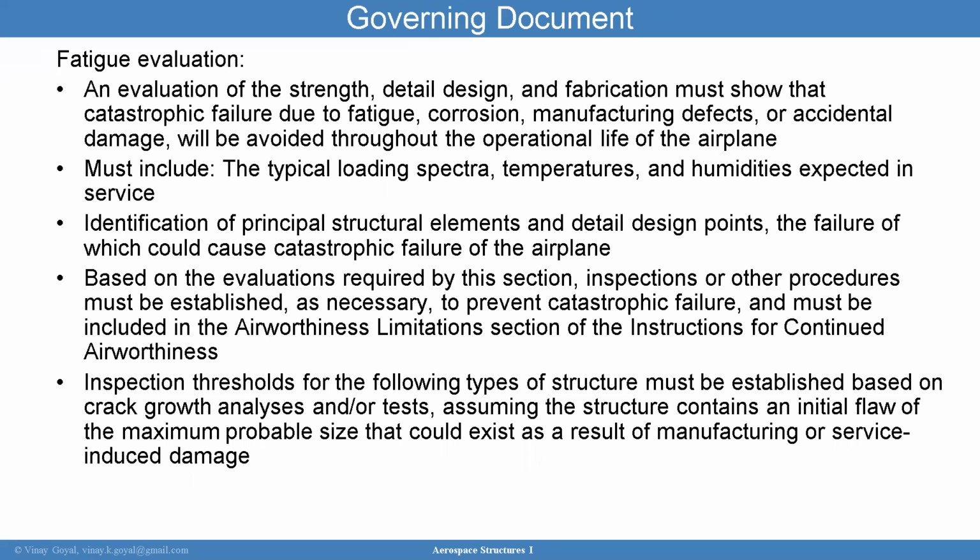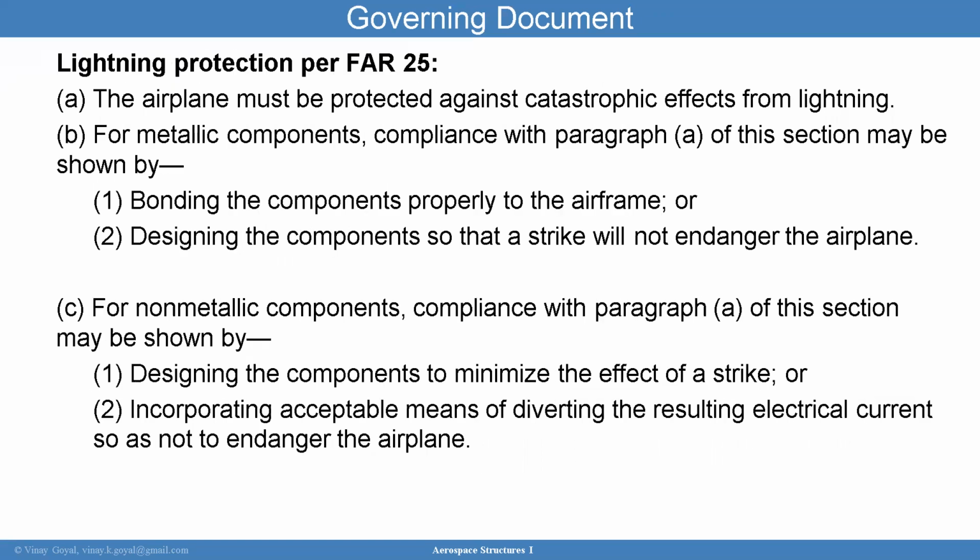So again, you need to make sure that you have identified every single point of failure that could cause catastrophic failure. You also need to define the load spectra, the temperatures, and humidities expected in the service life, because that can play a role in that test program. And so again, you want to make sure you're designing against catastrophic failure due to corrosion, manufacturing defects, accidental damage like impact damage, lightning strike, and you need to account for all of that.